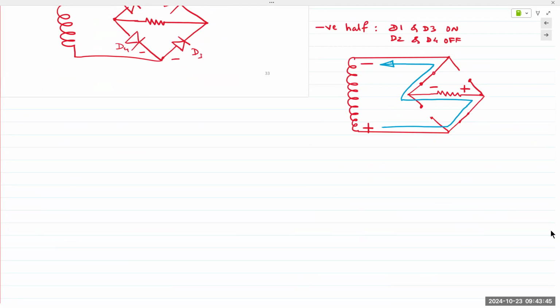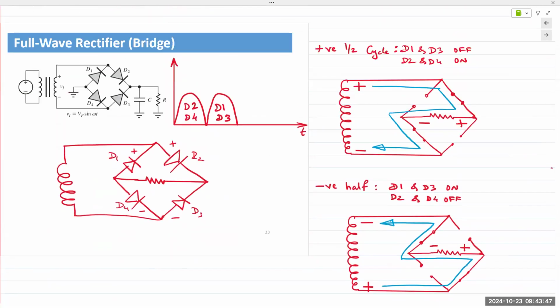Because there are two diodes in a bridge rectifier circuit for every half cycle, the turn on voltage is now twice as much, right? So 0.6 times 2. That requires 1.2 volts of the input signal for the diodes to actually even turn on. If the input is less than the diode turn on voltage, it's not going to turn on.